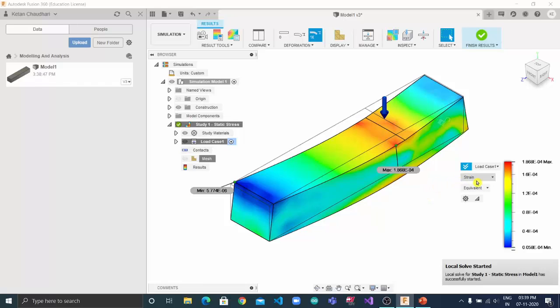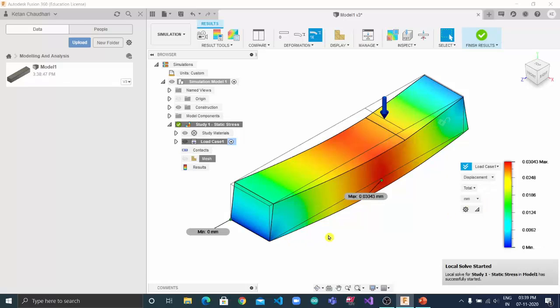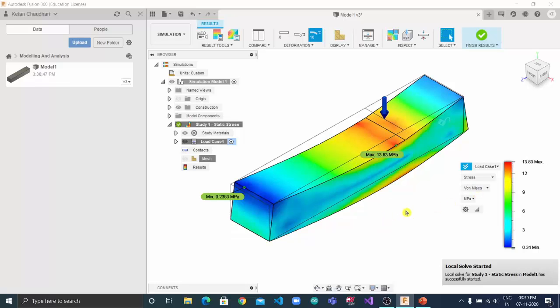Let us check displacement. Click on drop down and click on displacement. We get displacement at 0.03043 mm. Again go to stresses. Now let us check our stress value at 20 mm from left end and 110 mm from right end.